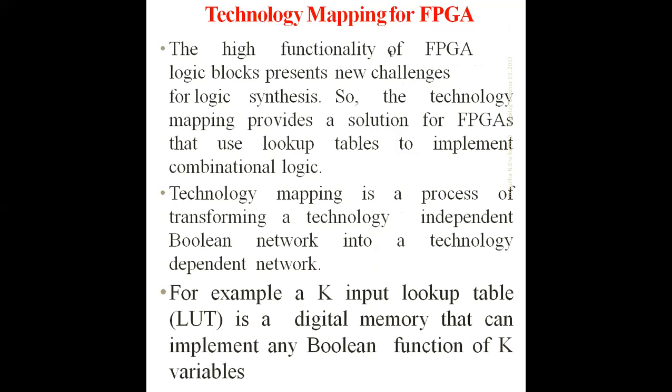Okay. Next, today's topic will be technology mapping for FPGA. What is meant by technology mapping? What is the importance of this? We'll see that. First, technology mapping. The high functionality of the FPGA logical block presents new challenges. We need high functionality at the output side for logic synthesis. So technology mapping provides a solution for the FPGA that uses a lookup table to implement combinational logic.